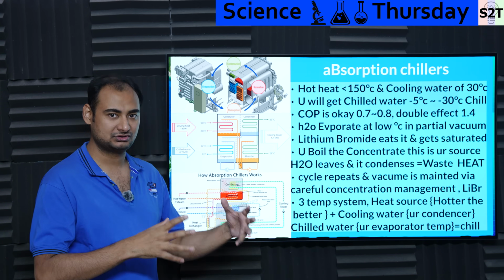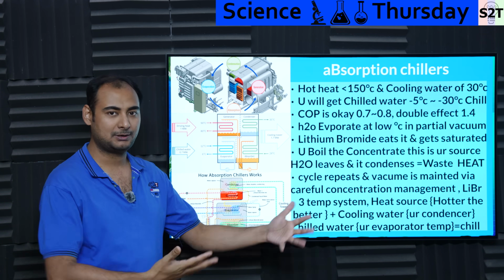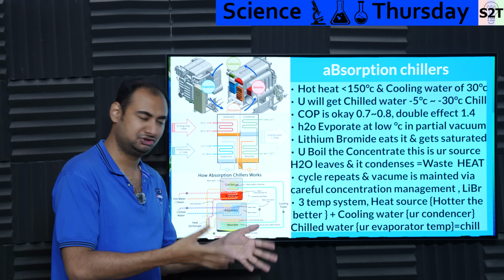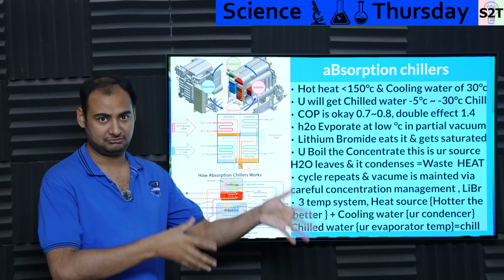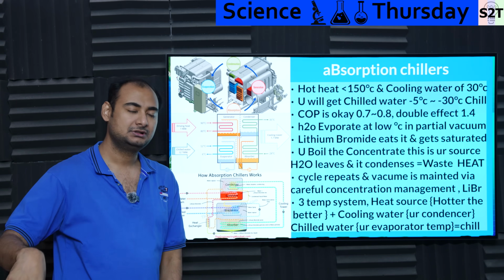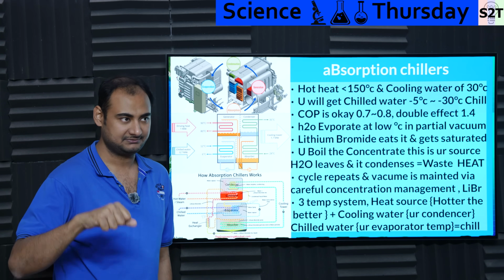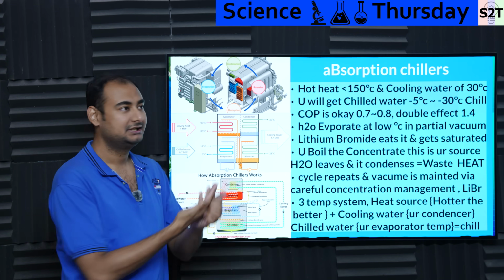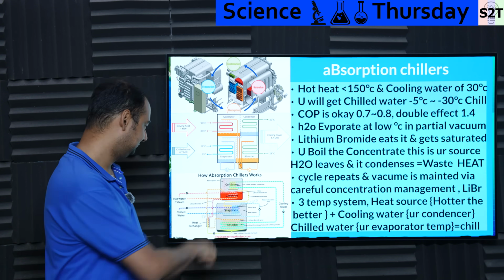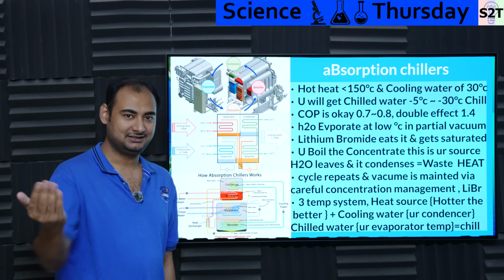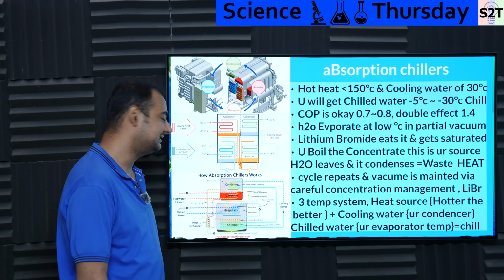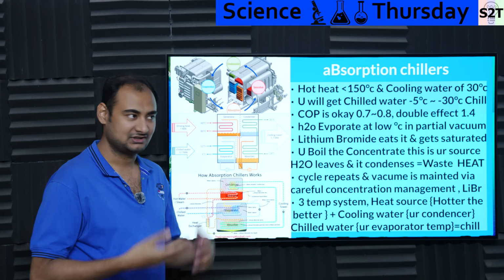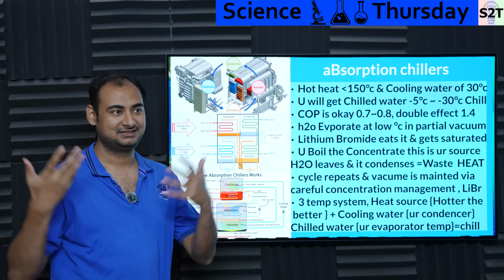So if you have a heat source that is just regular, like a coal power plant that runs 24/7, this is your guy. For example, in New York, they have power plants, and the waste heat is dumped into the city heat system. What if you have district cooling, and instead of getting steam, you are getting this absorption chiller chilled water? 12 degrees Celsius is input temperature, output temperature is 6 degrees Celsius. You get cooling, and this turbocharges your energy efficiency, because otherwise people will use electricity to run the AC. What's the point?